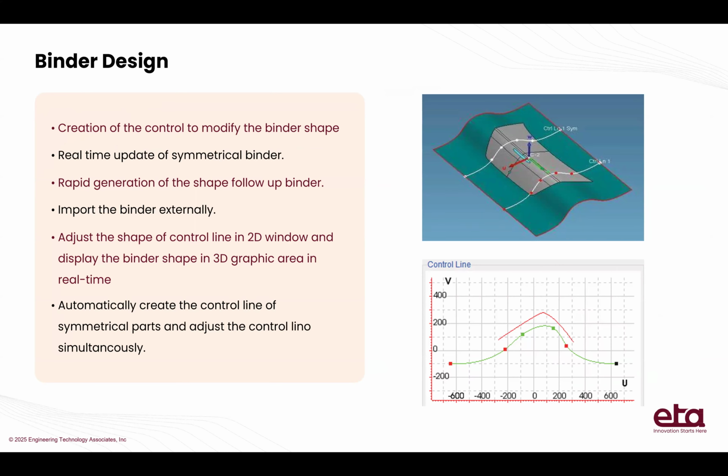Then binder design: the user can create a flat binder, a curved binder, or a user-defined binder. Drag a 2D control line, and watch the 3D binder update in real time. If you need symmetry, we can also mirror the control lines automatically.